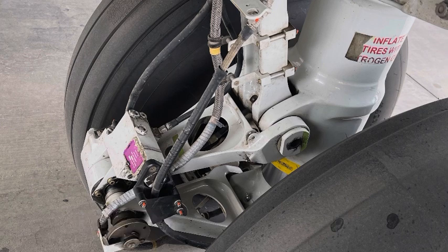A smooth landing will cause these two linkages to have excess vibrations. Excess vibration will cause the internal structure of the shimmy damper to create some fine cracks, and these fine cracks will cause the shimmy damper to break down in one of the landings, and the landing gear will be free to move and will cause, mainly, the collapse of the landing gear during the landing roll.